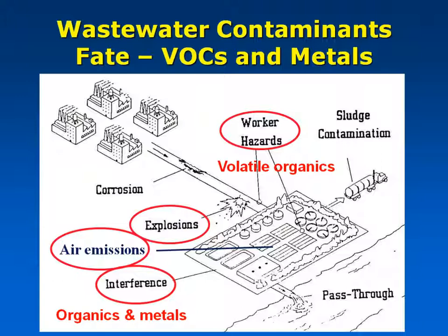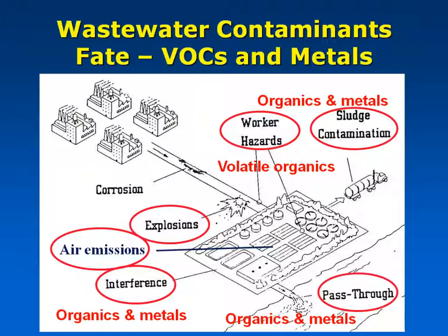We can also model the presence of organics and metals in the actual activated sludge basin to see whether there may be interference from some sort of toxic substance. We can figure out the concentration of the components that are going to be going out with the sludge hauling, and therefore by mass balance also look at how much is left over and is going out to your receiving water. And this is important for anything that may be considered to be an unhealthy EDC, endocrine disrupting compound, or so on.